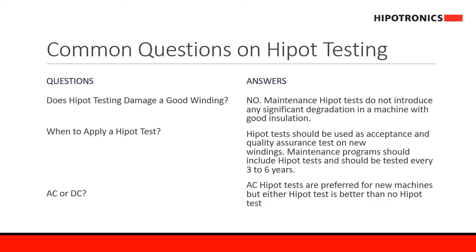After talking about some of the systems and solutions we offer here in Hipotronics for motor and generator testing, we will be now looking for some common questions on Hipot testing. The first question is, does Hipot testing damage a good winding? The answer is no. Maintenance Hipot tests do not introduce any significant degradation in a machine with a good insulation.